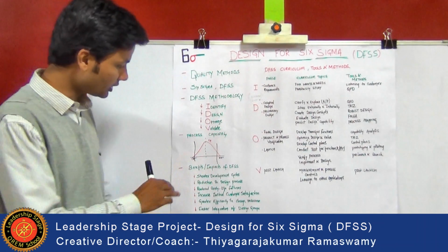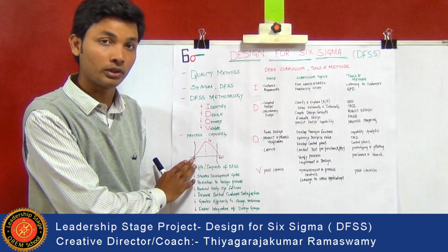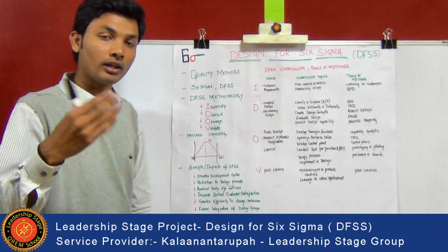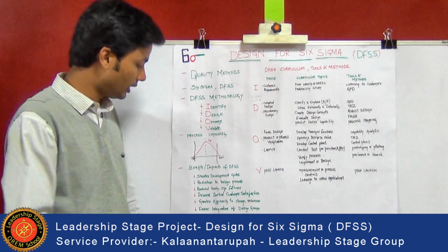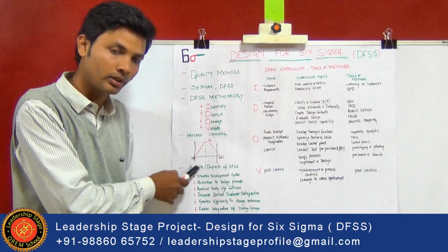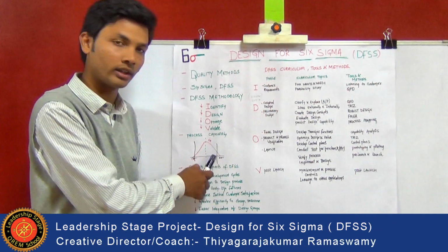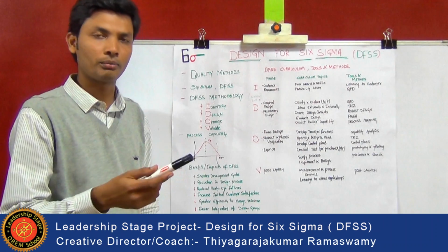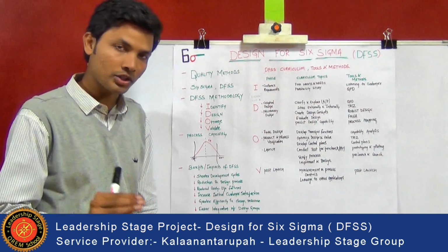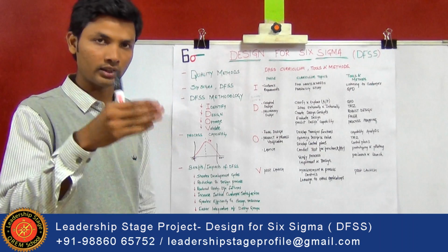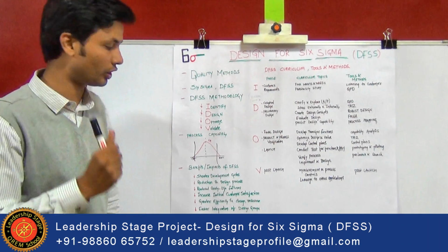Here is a standard chart diagram that we use for process capability, which is nothing but finding out its tolerances and quality limits, like -3 sigma and 3 sigma. The -3 sigma is the lower tolerance, and this is the higher tolerance, the upper limit and the lower limit. And then you calculate the Cp, which is the process capability for the dimension of that component: the upper limit minus the lower limit, divided by the standard deviation of the whole tolerances of the component.